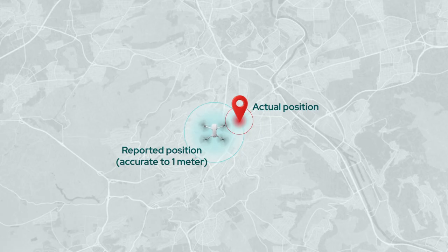The drone almost lies about its position by a meter, and that's a 3D bubble around the drone you have to imagine. Now, I'm just using a meter as a proxy; it could be 2 meters, it could be half a meter. It really depends on the conditions, and it can also vary between the accuracy in X and Y and the accuracy in the vertical, the Z, because one of the values might be coming from the barometer versus GPS. So a lot of different variables are at play here. But that's the core reason why you don't have absolute accuracy straight out of the box with drones.